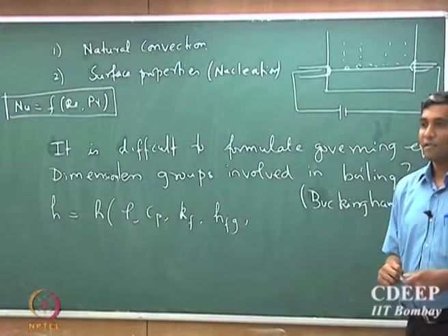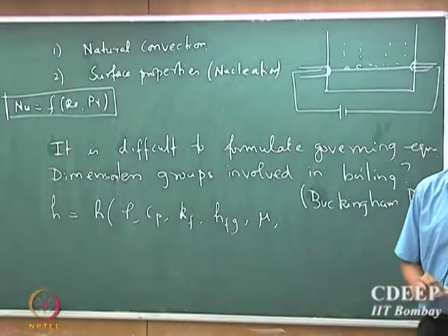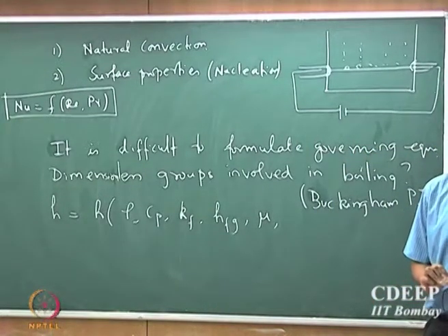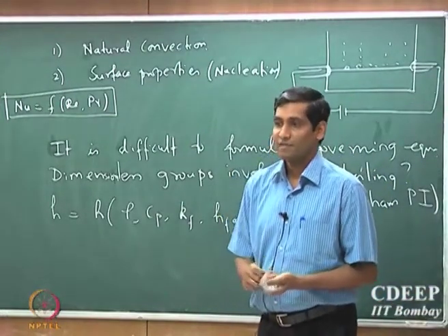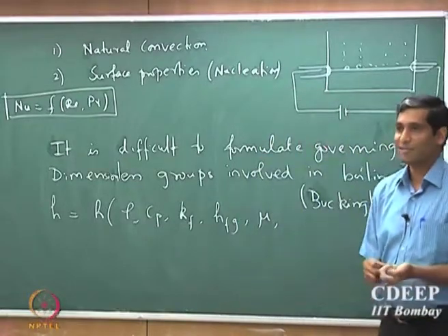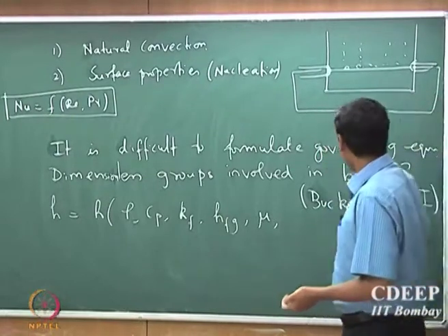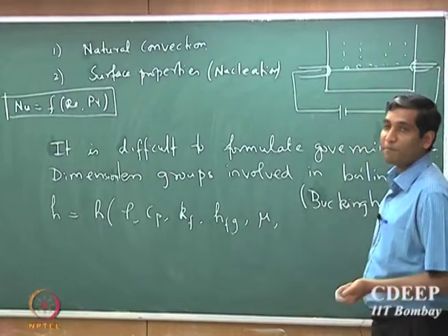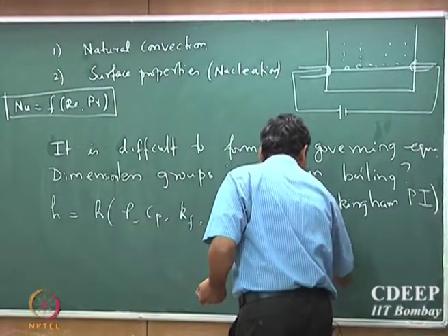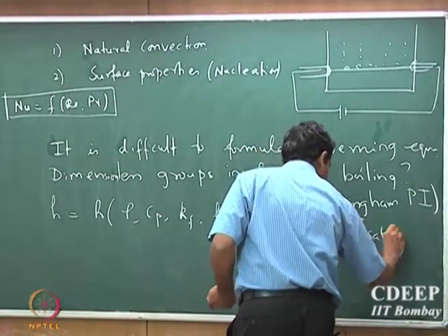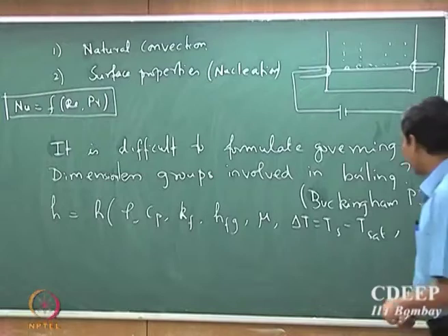So we got 4. Viscosity, why? Because of natural convection. Then temperature. What temperature? Is it the surface temperature? Remember that we are looking at the amount of heat that is transported. So that depends upon, no, it depends upon the temperature difference, which is the difference between the surface and the saturation temperature. That's the boiling point of the fluid. Okay. And then what else?